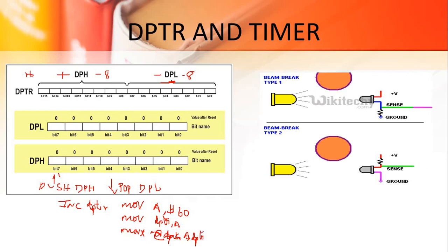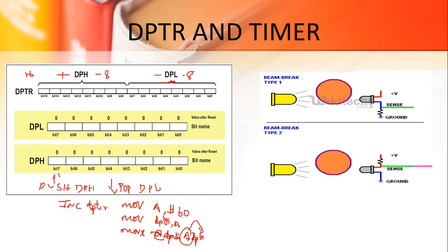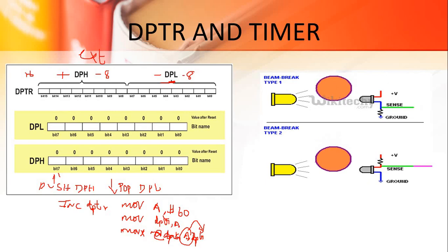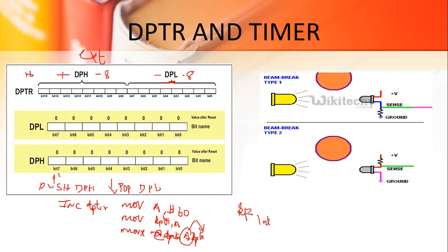Once all the operations are executed, that data will be stored in the accumulator. From the accumulator I move this to the data pointer, to point out the main data pointer location. This data pointer is an external pointer, and another pointer we have is the stack pointer, which is an internal pointer. That is, the stack pointer performs operations internally, and the data pointer performs operations externally.